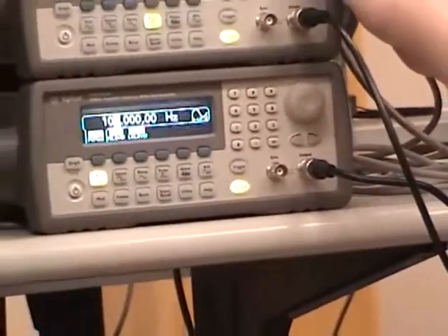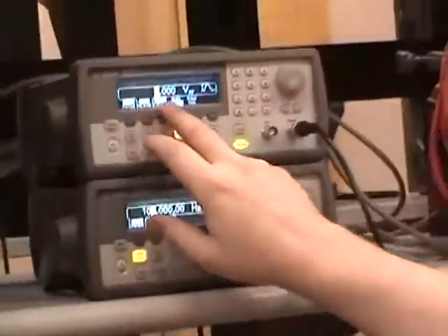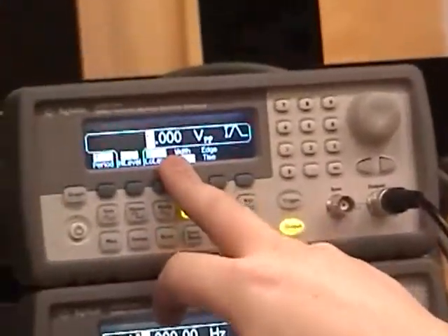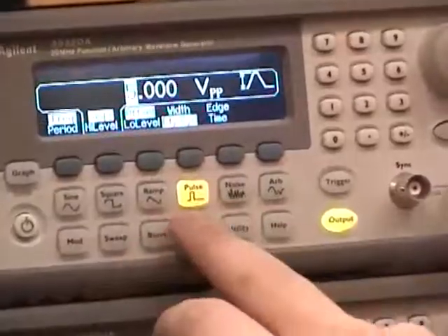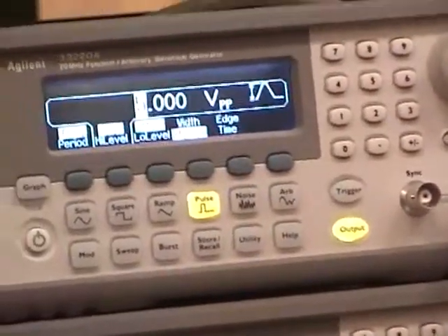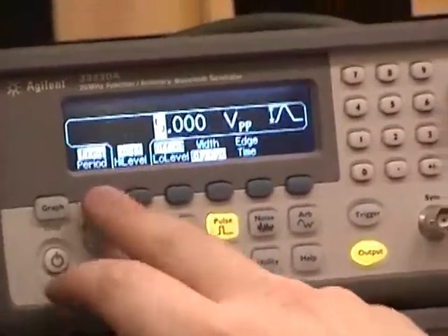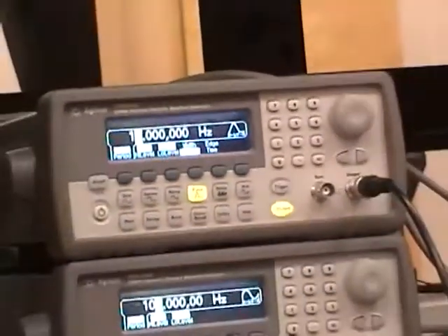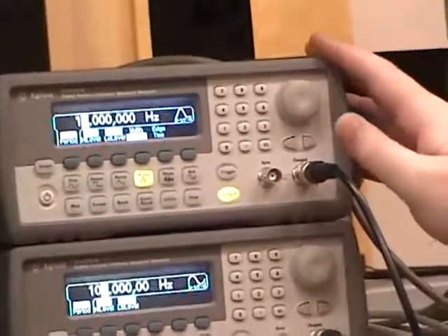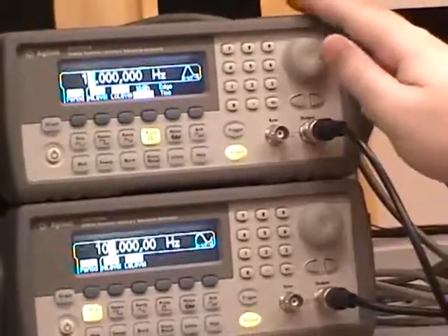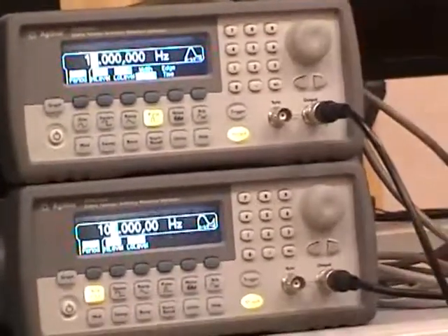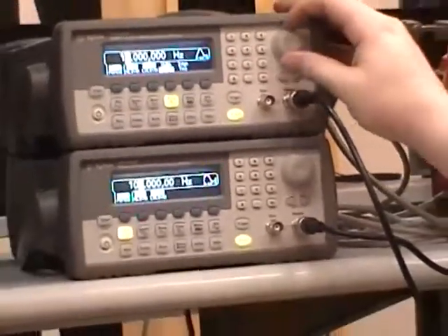And this power supply is outputting twice this value, so it's outputting 10 volts with a pulse signal, so it shoots up real fast. This is to simulate a similar type signal to what you would get off of a raw ignition coil, and it creates a lot of noise. It's being filtered out and into nice clean square waves for the microcontroller.